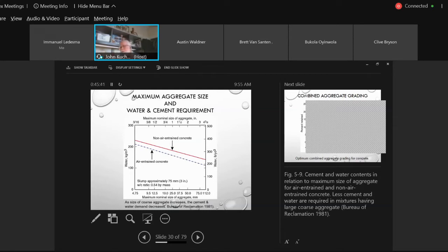guys worked on hydro projects up at Keenleyside or Waneta or any of the other ones, you've got mass concrete going in. You're going to use the largest aggregate you can to reduce thermal expansion, okay? Less cement, less thermal expansion. And thermal cracking, thermal problems in mass concrete are a problem. So here you can see a lot of things coming into play.